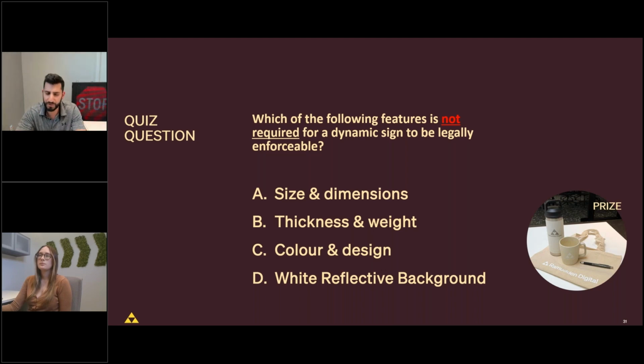They're very easy to maneuver, and we include brackets with each of our signs, with the cables, so they're quite straightforward to install. Compared to other larger products on the market, we have a fairly low profile. And again, with that 3-degree built-in down tilt, your field crews won't be spending a lot of time realigning this on the pole. Basically, put it up, make sure it's level, make sure it's square, and then drivers can immediately see the restrictions in effect from their car.